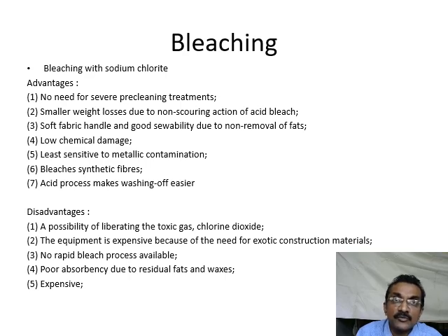It is expensive because it is a two-stage process of bleaching. The basic cost of the chemical is high. Equipment cost is also high due to the very specific equipment required. So the overall cost of bleaching is higher in the case of sodium chlorite.